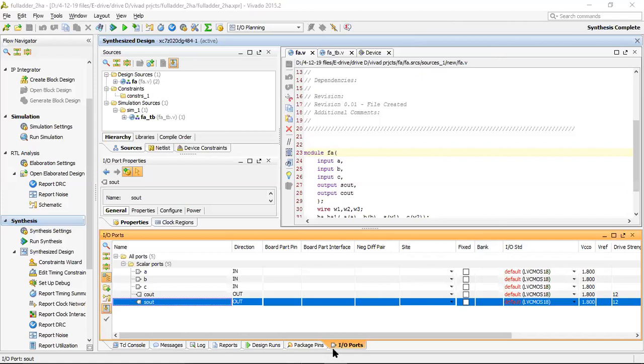See the DIP switches, switch 0 to switch 7. We have 8 switches, but from these I am using only 3. From switch 0, switch 1 and switch 2, I am using F22, G22 and H22.